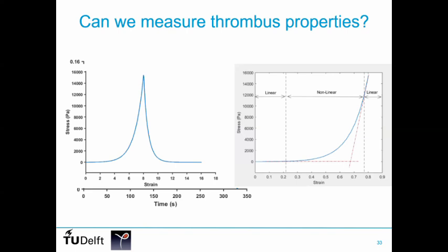I'm mentioning viscoelasticity and poroelasticity here. Interpreting these data is pretty difficult, we found out. So I'm going to stick to the analysis of the first loading curve, where we can potentially extract some meaningful data. If you zoom in here, in this first part, you convert it to strain and stress values, then you can see that there's a very long toe region, where the material behaves linearly and is very soft.